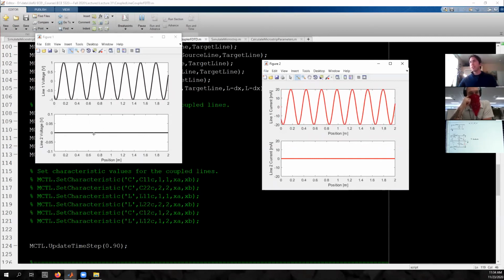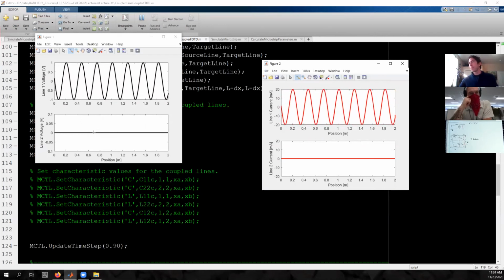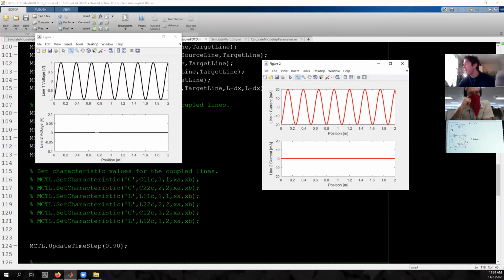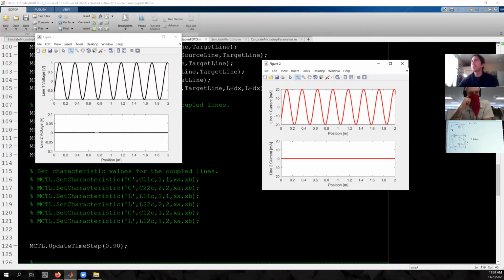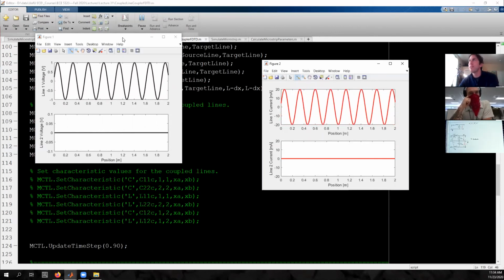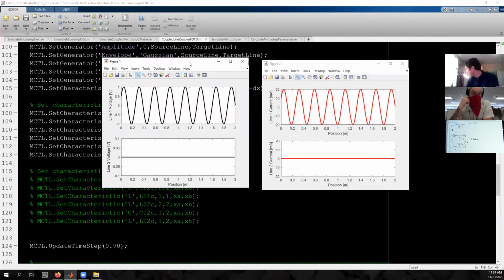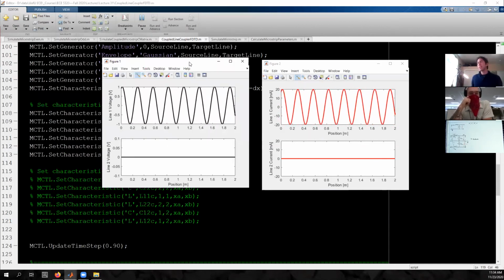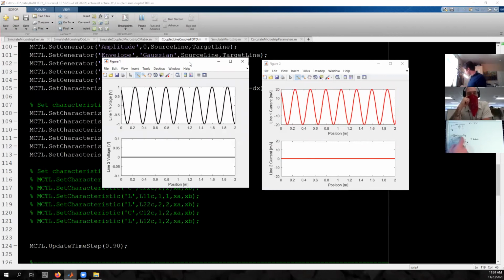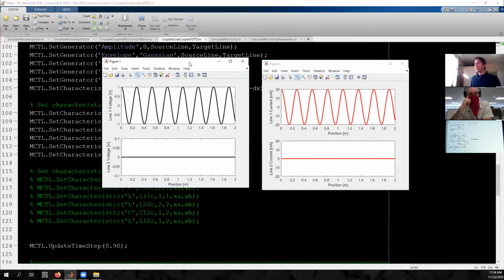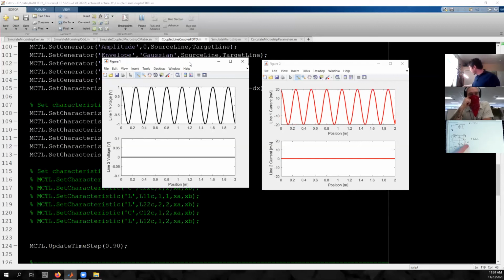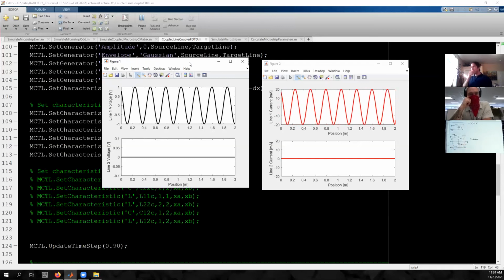And then the idea is you just fill in the appropriate parameters there for your coupled line, and we should hypothetically be able to simulate a coupled line coupler using this kind of FDTD model. So the only tricky part is using these electrostatic and magnetostatic simulations to insert the correct, I guess, diagonal elements, though that L12 and the C12 there.